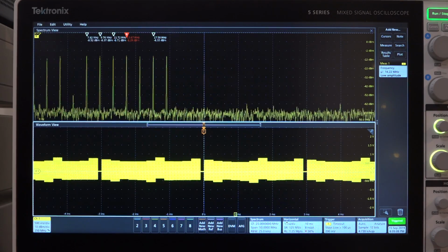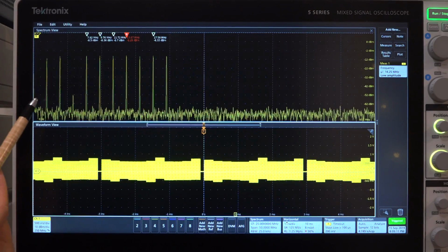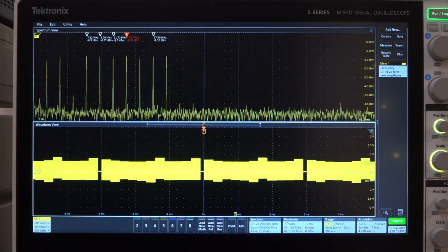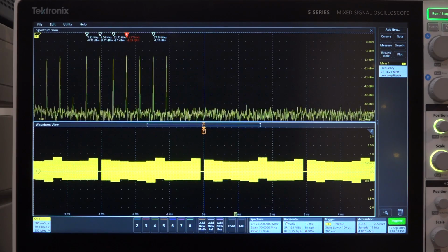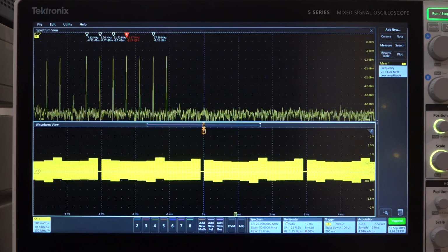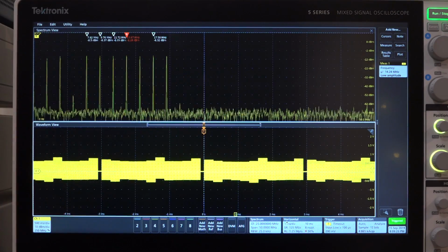And the amplifier, of course, amplifies that. Now if you look over here, you can see that we have already a worse missing tone test than we had before, even though we're producing less power. And I'm going to increase the power from the amplifier by reducing the attenuation, and have an eye out on what happens to this missing tone test.